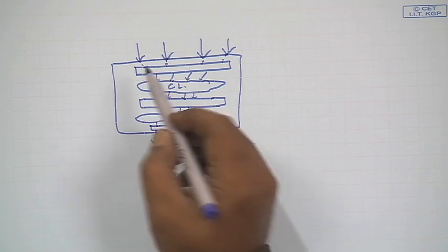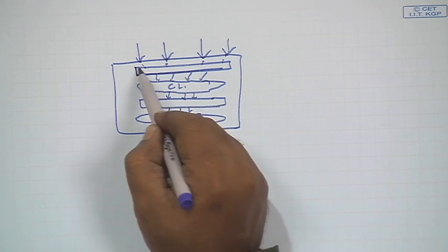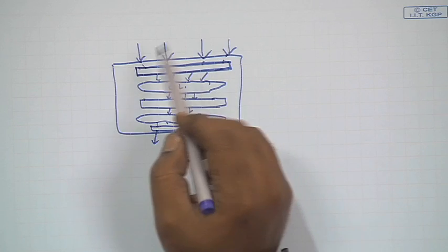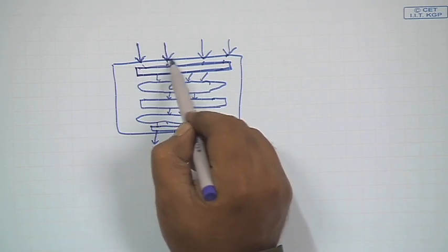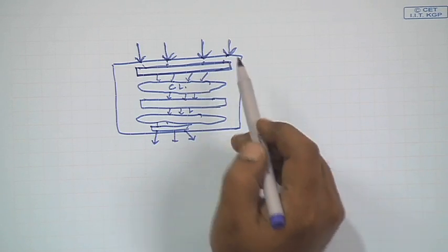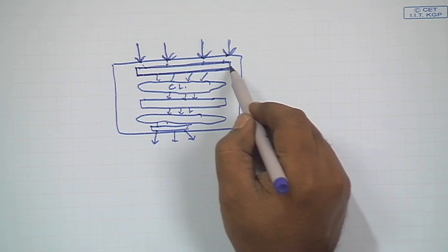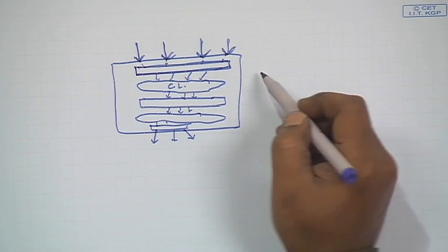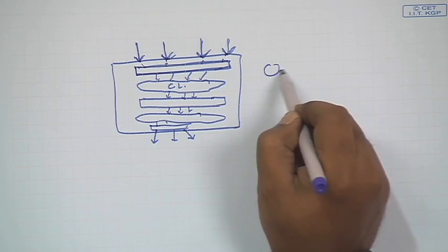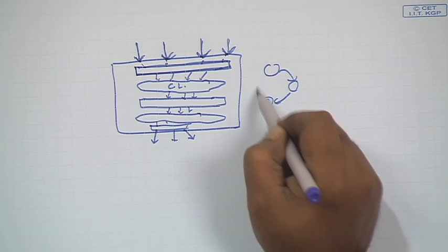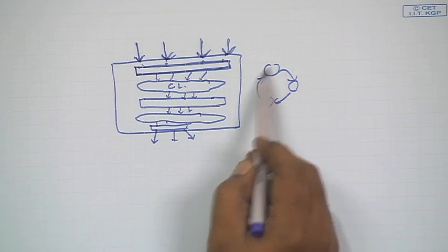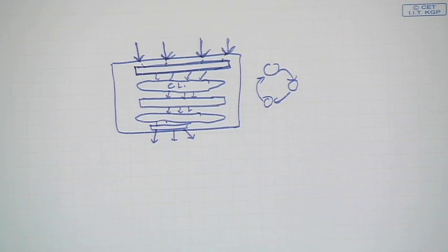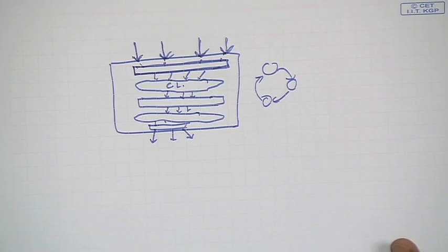So, that is why these data path registers are normally controlled by the primary inputs coming from the outside world. On the other hand, for controlling all these registers, combinational logic, etc., the control part is implemented by means of some FSM, so that at various states it controls the data path elements. So, I may need to test for a particular functionality.